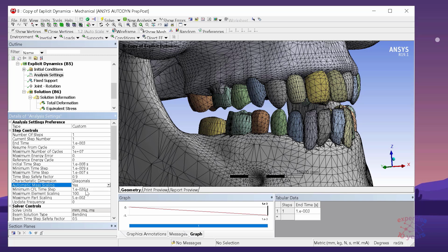And here, scaling. Of course, we'll put 8, and that's all. These parameters should somehow be remembered. Yeah, it depends also on the end time. If we increase the end time, we can also increase these values. Increase means instead of 1e-8, we can put 1e-7 or 1e-6.